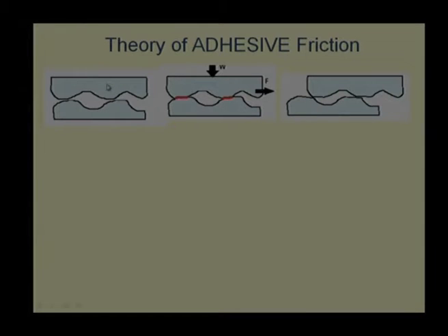Now, let us develop a theory where we are saying that when you are applying a force on one irregular surface against another irregular surface, they are going to undergo plastic deformation, and due to that plastic deformation there is a possibility of cold junction formation. This is cold welding under pressure. You are applying a force, and that is why this kind of welding is happening.